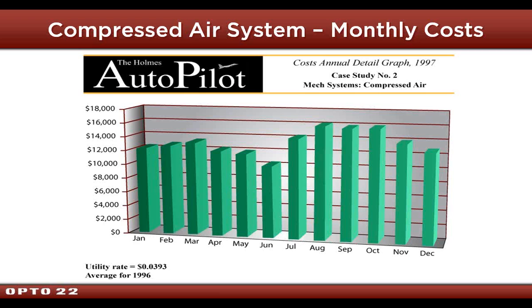And this wasn't automatic, it's not something they could do with automatic controls. They actually had operators in a boiler house controlling these. So they set our monitoring screen on their desk, and they controlled the sequencing of the compressors and which compressors are on and off under different load conditions: first shift, third shift, weekends. Within 1 month, the project manager at GE called me and says, "We've just saved $250,000."